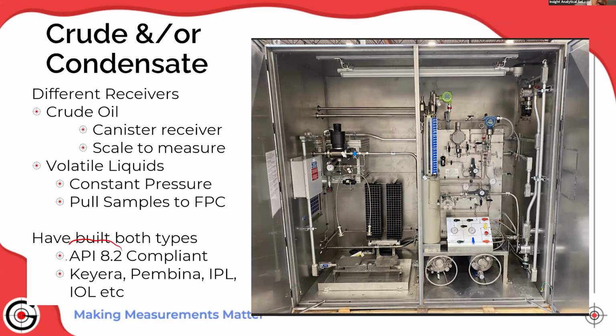They are all API 8.2 compliant. API, American Petroleum Institute, API 8.2 talks about how to properly pull a composite sample. So we make sure that we build it to meet all the requirements of API 8.2, and we've put these out for crude oil, for natural gas condensate, for spec propane being loaded onto ships. And we're happy to customize them to meet specific application needs for anybody's application.